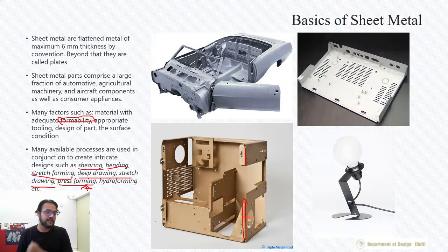The other thing that I want you to notice are these holes that are there in these kinds of corners. These are relief holes. For example, if you are bending this part like this, and there was no hole, then when you are bending this, this bend would interfere with that bend and the material would crumble at this corner. So because of that, these relief holes are given.